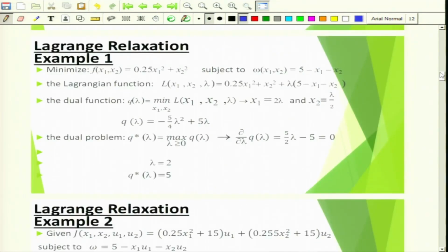Now let us take up a simple problem, but here it is a continuous function. Why we are discussing this Lagrangian relaxation approach is very important because the unit commitment problem is a discontinuous problem. Generator is on or off, it is a discontinuous thing. For a discontinuous kind of problem you cannot have differentiation directly, so you should deal with them individually.